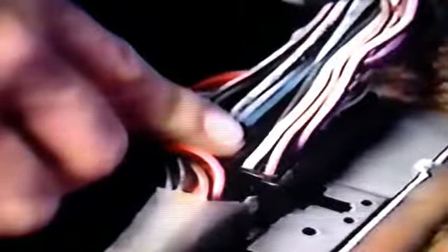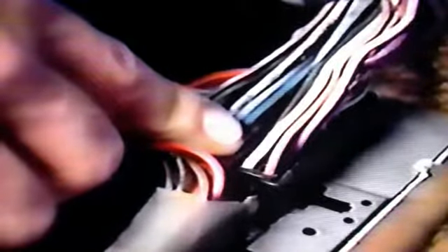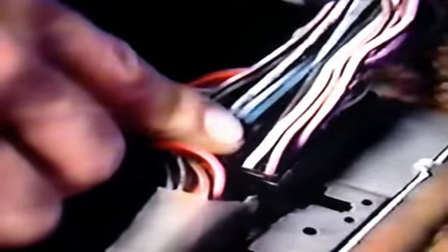To get to terminal 18 on the ECM, take your meter inside the car, usually on the right-hand kick panel. On the test engine, the ECM is right out here where we can reach it. The terminal at the ECM can be back probed by lifting away the plastic wire covering. There is no weather pack seal to worry about damaging, so it's okay to take a little screwdriver and back probe at terminal 18. The meter again shows us 12 volts.